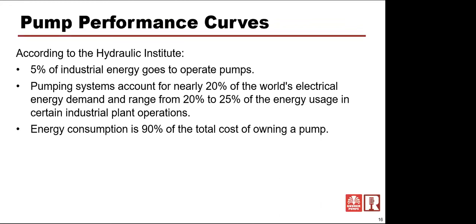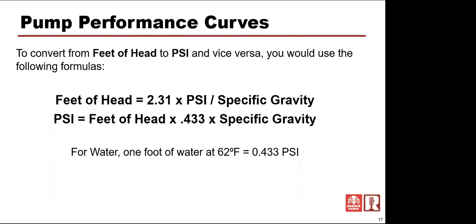That is a very significant part of their energy consumption. Energy consumption is estimated, of course, and it's going to vary on the type of pump and how often it's operating and all that kind of stuff. But energy consumption oftentimes is as high as 90% of the total cost of owning that pump, including purchasing it. So how efficient that pump is is extremely important in design, and oftentimes it's an overlooked part of the design.